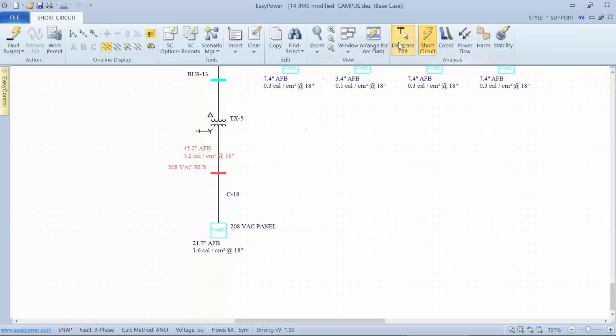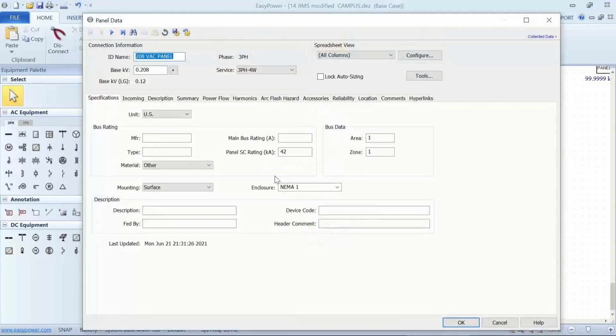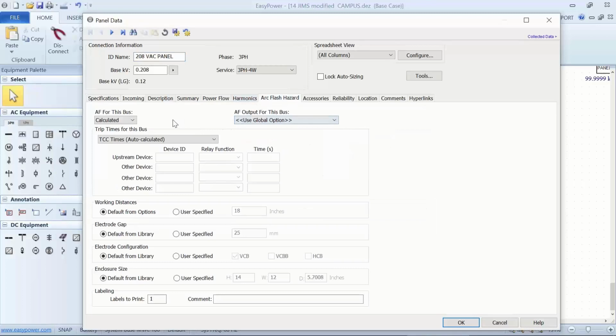So what I'm trying to point out, if I go back to the Arc Flash dialog box for this particular panel, is that in my humble judgment, looking at the current that's involved, I have justification for limiting the calculation times using a user-defined time of 1/2 second for just this particular system.